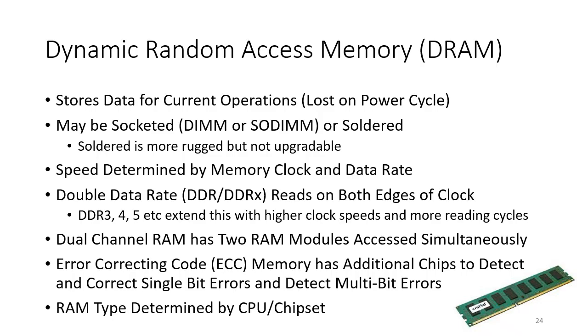So these days we often see socketed RAM, so either a dual inline memory module, or possibly in a laptop you might see SODIMMs, which are a more compact version. You can also see soldered memory. Soldered memory is a lot more rugged, but you can't upgrade it in the field. But we often see now in modern laptops and industrial PCs, we do see soldered memory. It's more covered for shock, vibration. But as I say, the downside is it can't be upgraded. So that means if you buy your computer with soldered RAM, you can't do much about it in future. You're stuck with what you get when you bought it.